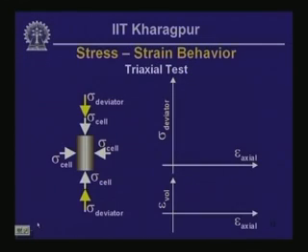So, on the left is shown the schematic of a triaxial specimen, and that is subjected to an all round cell pressure and an axial deviator stress. So, let us begin the first test. So, what happens, we increase the deviator stress marked with a yellow color there, and we gradually increase that deviator stress. We take the sample to failure, and what we get are those responses.